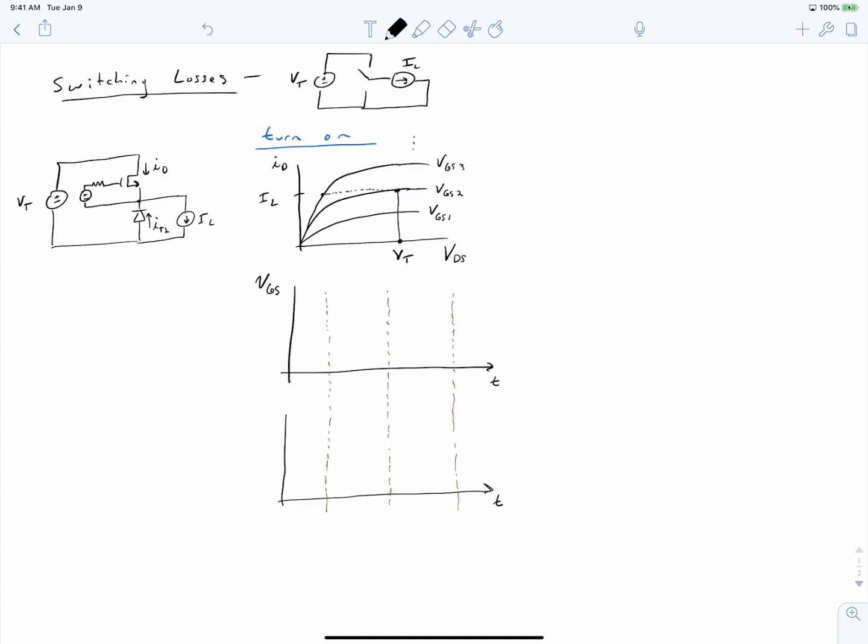And so initially when we turn the gate driver on, the gate driver goes to perhaps VGG. But charging the gate up involves charging up this RC network. So our equivalent circuit of our MOSFET with the gate resistor is as follows. We can talk about there being a capacitor between the gate and the drain.